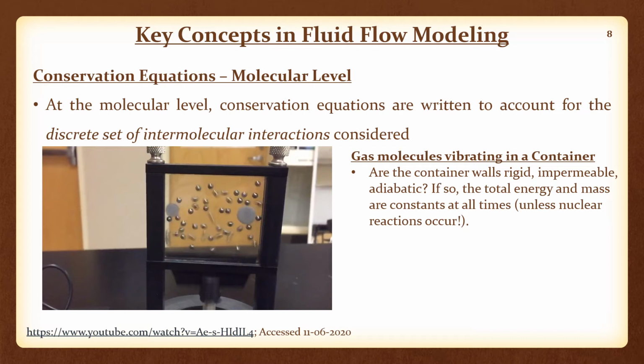There is always some interaction, intermolecular interactions. These interactions are typically in the form of secondary bonds, ranging from van der Waals interactions, some induced dipole type, induced quadrupole type interactions, to then permanent dipole based interactions, then stronger such interactions like hydrogen bonds, and then if there are ionic species that are present, then ion dipole, ion induced dipole, and then ion ion interactions as well, right? So these are the kind of secondary bonding interactions that create a certain potential energy of interactions.